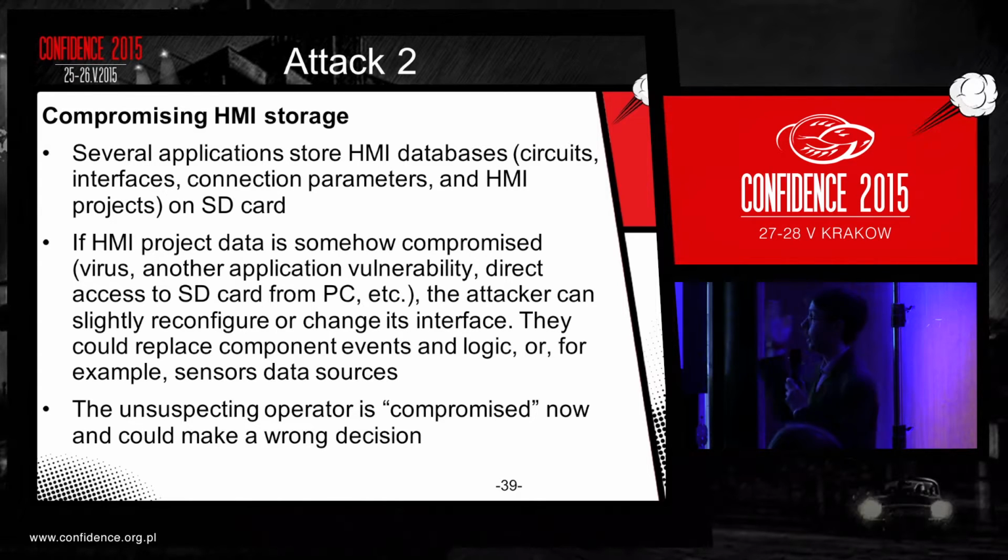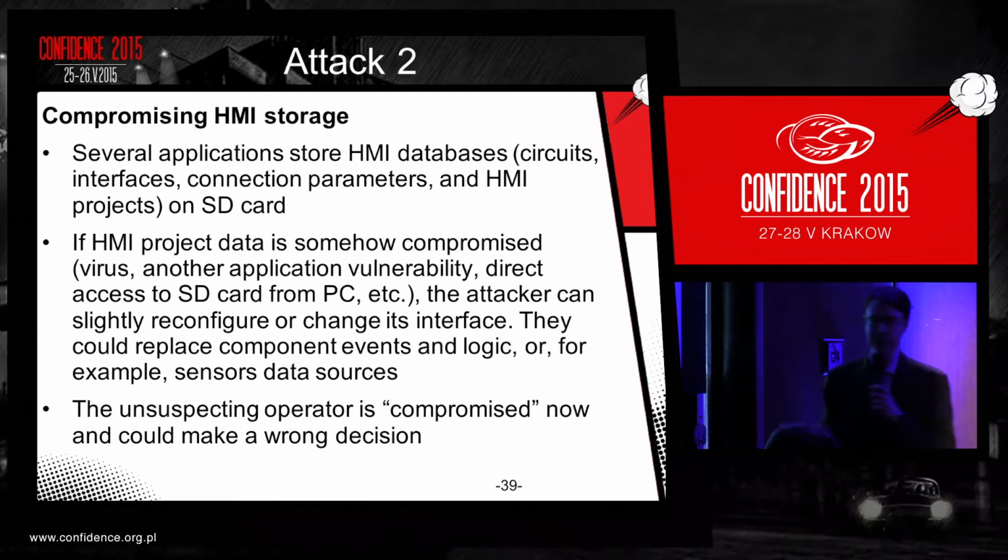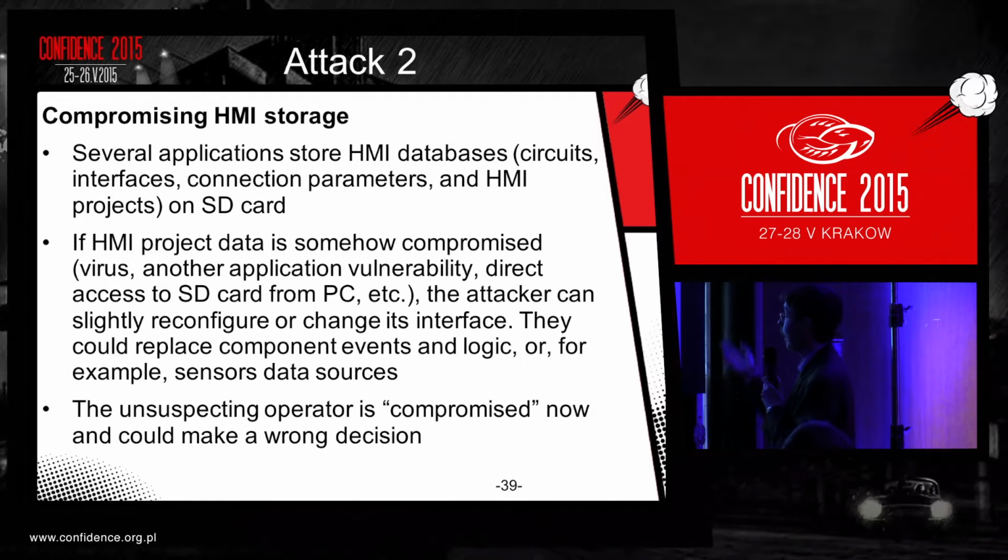If the SCADA project data is somehow compromised, for example, by a virus, another application vulnerability, for example if the application was compromised through the double free, direct access to the SD card from a PC, or if the SD card was swapped intentionally, the operator puts the phone on the table and someone quickly swaps the SD card, the attacker can slightly reconfigure or change the SCADA interface.